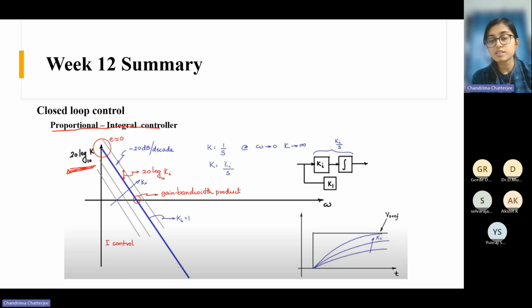So the signal is getting attenuated at the higher frequency region, right? So this is a good response, better than the previous one, because it is giving us what we want. At DC, it is giving us high gain, and at the high frequency region, it is giving attenuation. What kind of controller gives us this kind of frequency response?